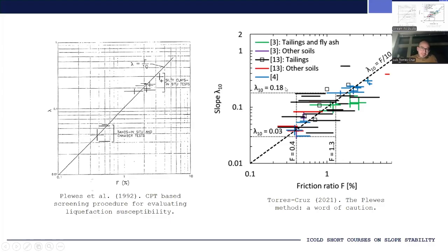Of course, it's never going to be 0, but let's just assume that it is 0. And how high can it go? The data shows us that values of lambda in non-plastic soils can go as high as 0.3. That's a bit of a push, but let's accept that. So the credible range of values goes from 0 to 0.3.